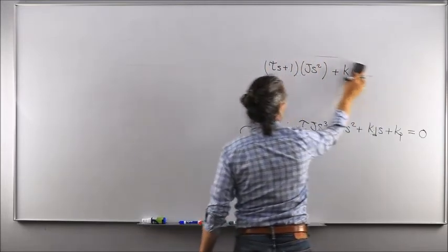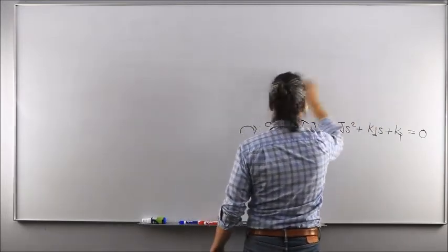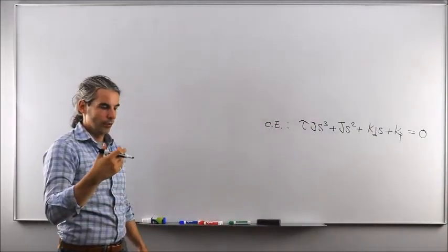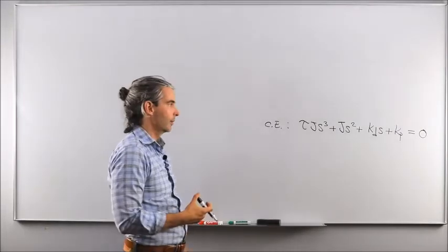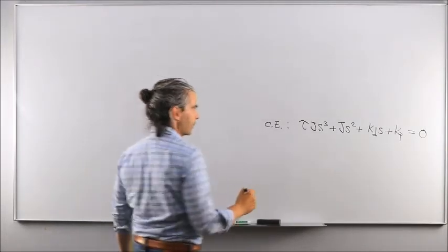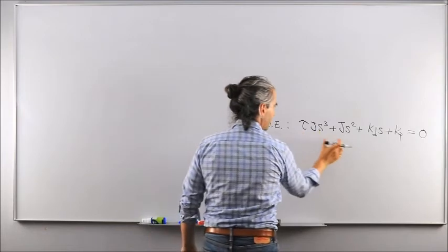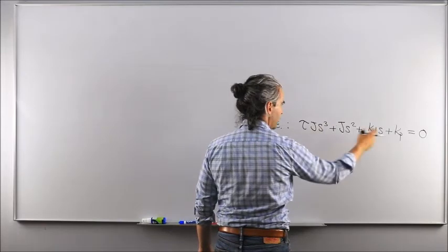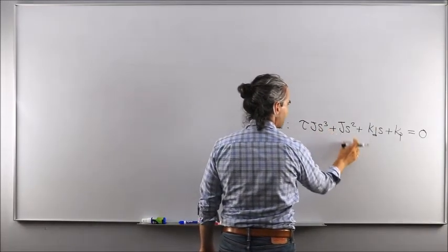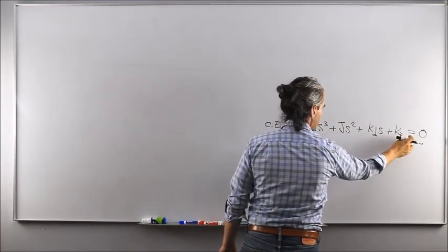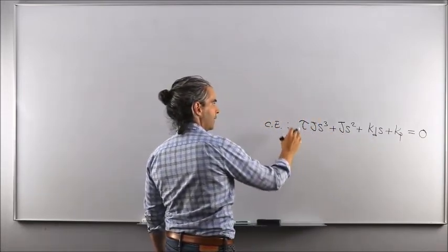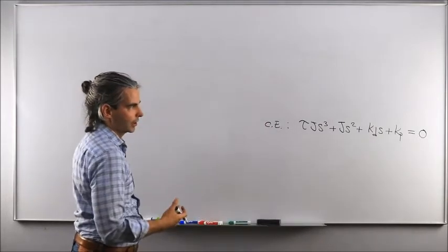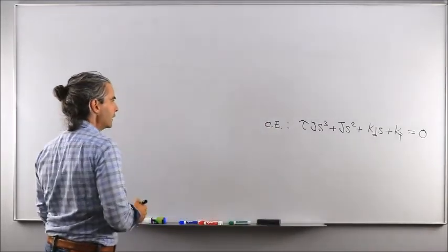All we want to know is whether this transfer function representing the entire system in a closed loop fashion will be stable, unstable, or asymptotically stable. Well, first off, quick trick again: you look at the coefficients to make sure that there's nothing missing and that you don't end up with a negative. So we have our s cubed, s squared, s, and s to the power 0. They're all there, and furthermore, they are all positive. So we cannot draw any conclusions at this stage, so we need to do the full array.